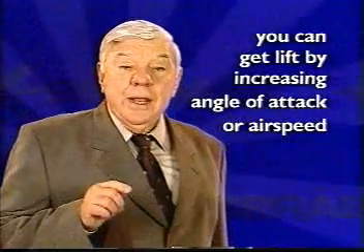Remember that basically you need more lift to get out of the increased rate of descent and go back to the proper flight path. And you can get lift by increasing angle of attack or airspeed. To increase angle of attack, your airspeed must be acceptable, or the extra pitch will take you to the backside of the drag curve, and the resulting sink rate will be higher. The final solution is thrust, but it may take a lot of time, so this option is practicable only at a safe altitude. To keep away from the potential development of high sink rates, fly the stabilized approach concept.